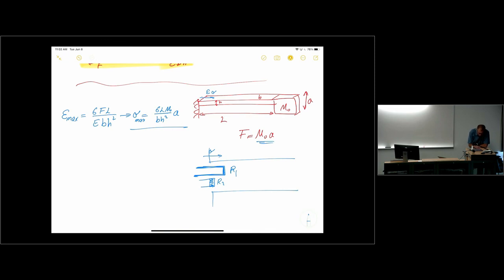So for R1, I can see that delta R1 over R1 is pi L sigma L. I go back to the equations that I had on the previous page, plus pi T sigma T, right? And sigma is sigma max in this direction. I don't have sigma T, right? I'm assuming that the device is deflecting with the main substrate. It could be a part of it. So for this situation, I don't have sigma T. Sigma T is 0. Sigma L is sigma max. So this is just pi L sigma max, which I have from here.